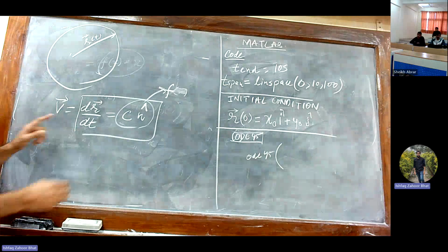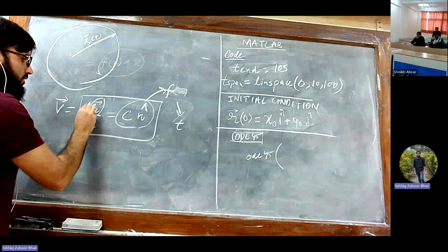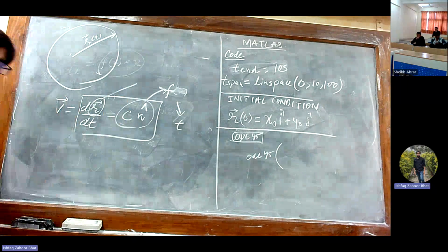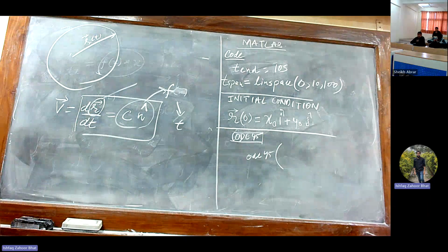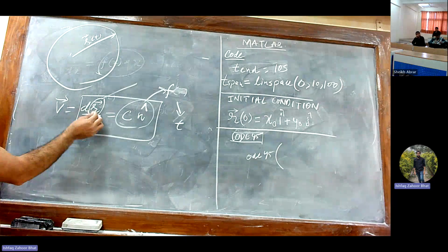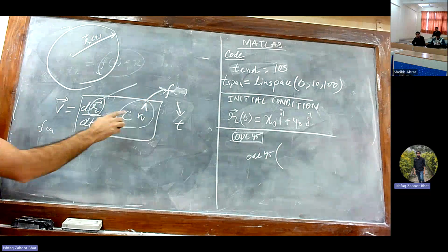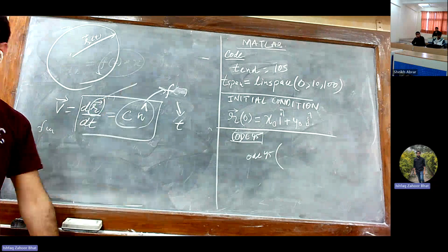And what is our variable here? t is our variable, and what we need to integrate is this r to get the value of r. So instead of y, we have this r. The next thing is that you will write this function somewhere where you will calculate this f, and you will feed it back to ODE45 to integrate it.